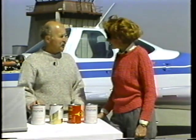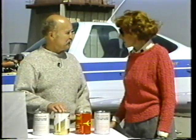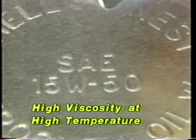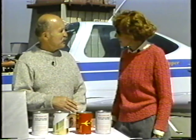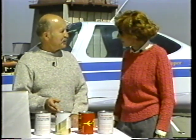The higher the viscosity number, the more resistance it has to flow. Some of the manufacturers are now coming out with multi-grade oils, and this type of oil acts as a low viscosity oil at a low temperature and as a high viscosity oil at a high temperature. This also enables you to operate your airplane from a low temperature area to a high temperature area without changing the grade of oil you're using.